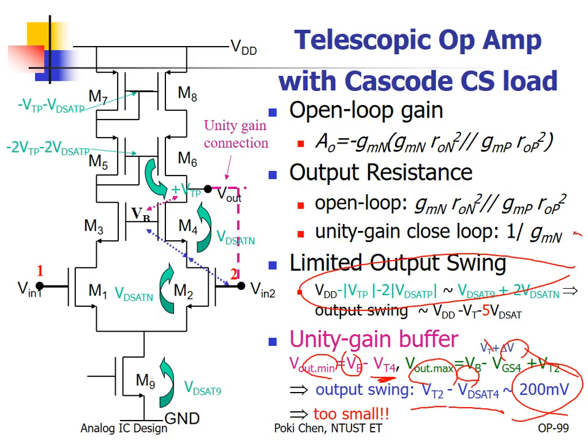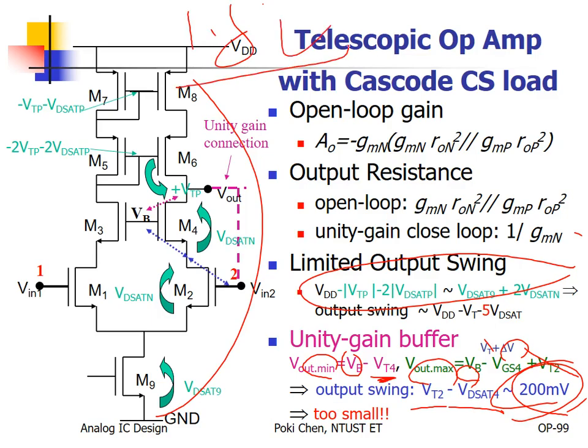How much you can get? 200 millivolts, I think. Yeah, it is large enough for such kind of situation. Okay? Sometimes even smaller than this. Wow. For 0.18 micron process, 1.8 volt supply voltage, the best operation range for your voltage buffer is only, only 1/6. That's really sad. So lesson 1.